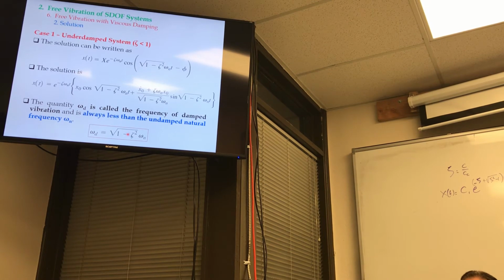If you wanted to, for example, hit a bump and then oscillate, you want it to be under damped. If you want to hit a bump and stop abruptly, you want it critically damped. But if you want it damped, yet it takes a long time to go back to zero, it's like you hit it, but it dies down slowly, we call this over damped. The only one that has any oscillation is the under damped case, in which you can still have variations in the oscillations. So under damped means, remember what zeta is? It is C over Cc.